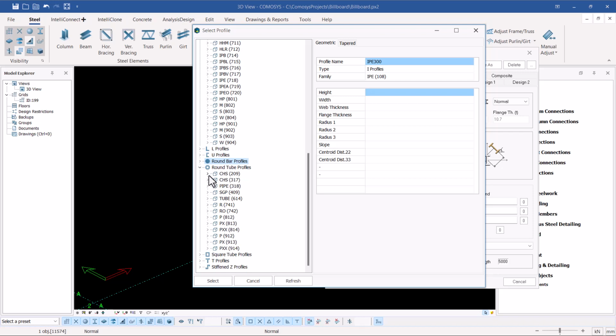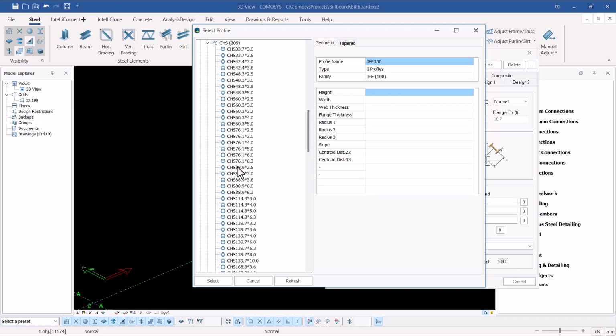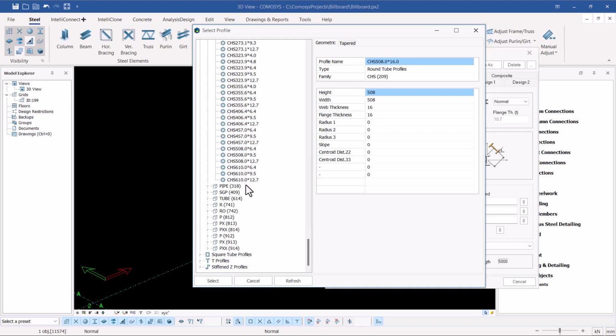This is circular hollow section. I'll click on that drop down arrow to have a look at another huge family of circular hollow sections. Let me scroll down. My target is 610. I'm here in 508, and if I come to the bottom end here, I'll be able to get to 610. Remember, it's hard to get a full pipe with this diameter. Normally you buy an MS plate of this particular thickness, 6 millimeter, and you roll it to form a pipe and weld it together.